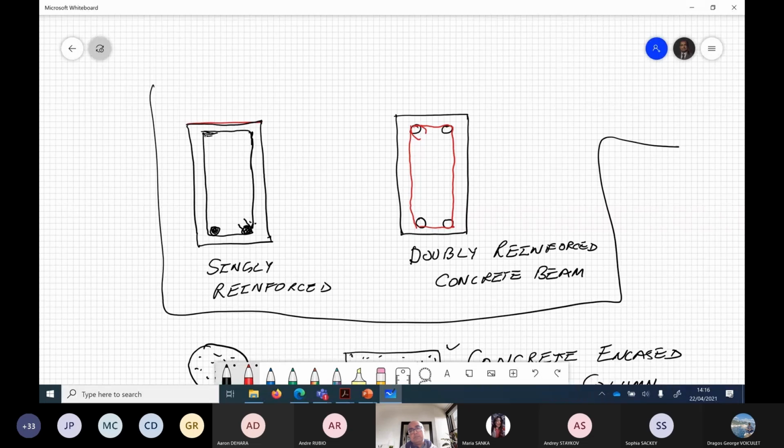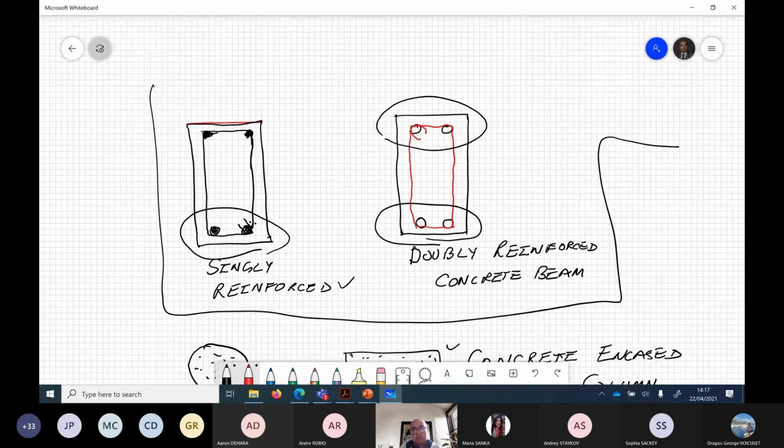So in today's lecture, I'm going to complete the example for singly reinforced concrete beams. Now here you would say to me that if we have tension reinforcement, we have this stirrup or shear reinforcement, a ring, how do we hold this ring? So normally, if compression reinforcement is not required, we use very small diameter bars to hold the stirrup, but these are not required. What we are dealing with here is this part, the tension reinforcement, and in doubly reinforced you will have this bottom tension reinforcement as well as this compression reinforcement.